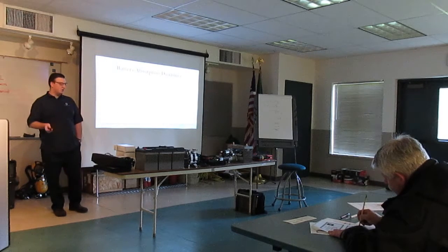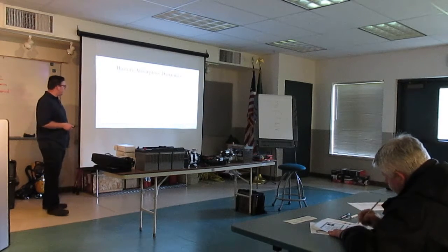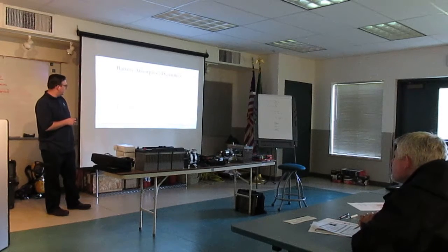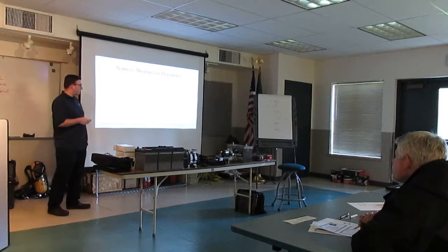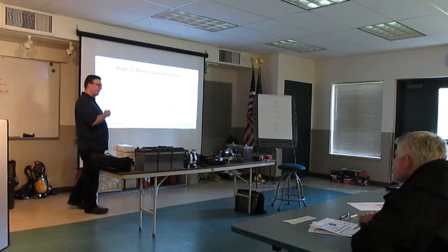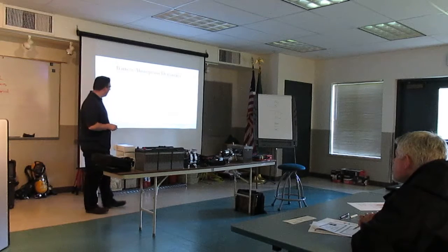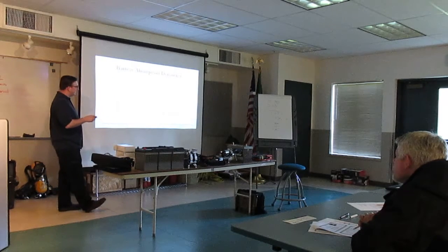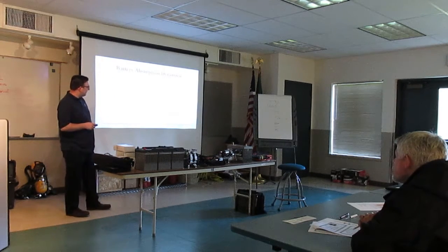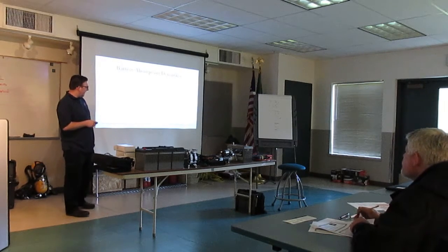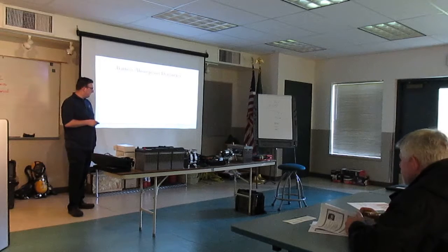So, some battery absorption dynamics. Your conventional charging, your average performance for all situations, undercharges at low temps and overcharges at high temps. Your set point is set at a standard point. Optimized or smart charging, we get back to that 3-phase change, is constantly charging to the natural battery dynamics, which eliminates your overcharging and undercharging. And your profile is specific to battery temperature.